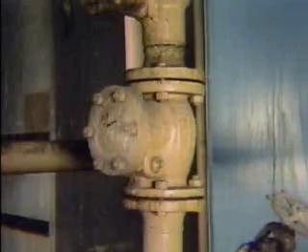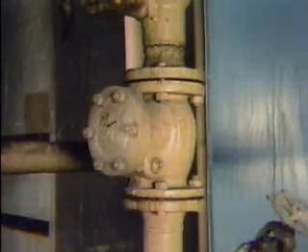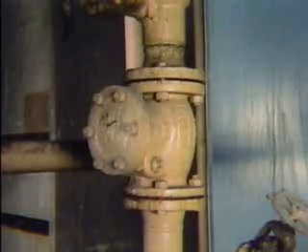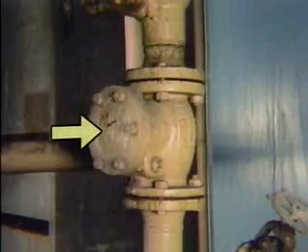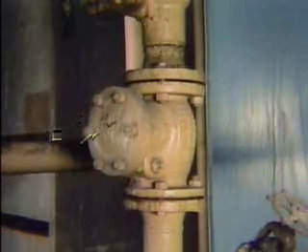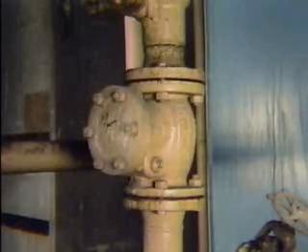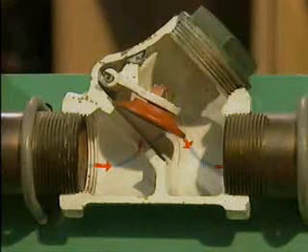The body of a check valve is similar to the body of a globe valve, but most check valves don't have stems, handles, or hand wheels. Most check valves do have replaceable seats, discs, and caps. The cap is the top part of the valve body, which can be removed to provide access to the disc for maintenance. It's essentially the same as the bonnet on other types of valves. Several different types of check valves are available. We will look at 3 of the most common.